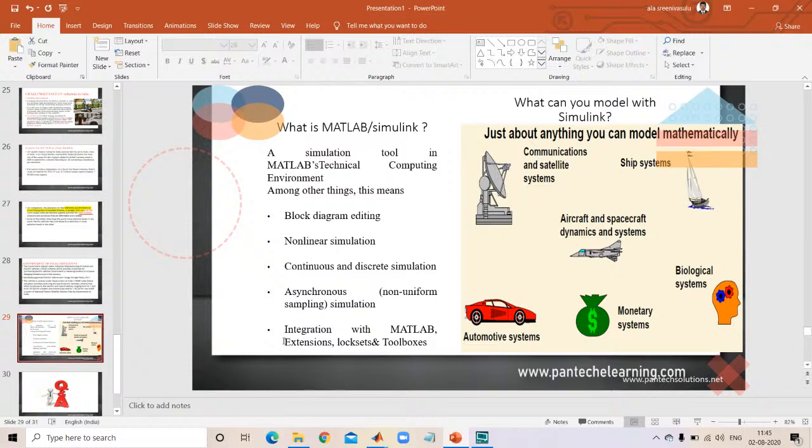So when you are implementing a multi-phase machine, automatically you need to implement a multi-phase input supply. You need to implement a multi-level inverter. But why do we need a multi-level inverter? When you are using a battery DC voltage, you need an inverter to convert that DC into AC, right? So compulsorily you need one inverter. That multi-level inverter will convert DC into AC. Then only the motor will drive.